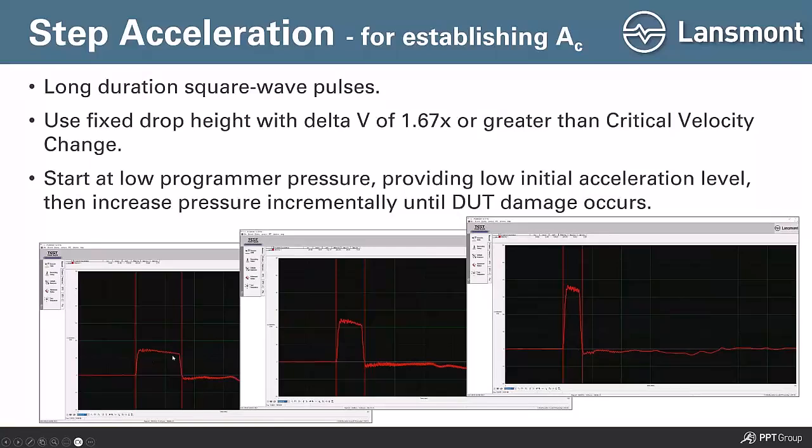But remember, the area underneath these is equal to the velocity change. So if I looked at the value, which it's too hard for you all to see, the area here is basically equal to the area here, which is equal to the area here. And so the velocity change numbers for each one of these shock pulses is basically constant.